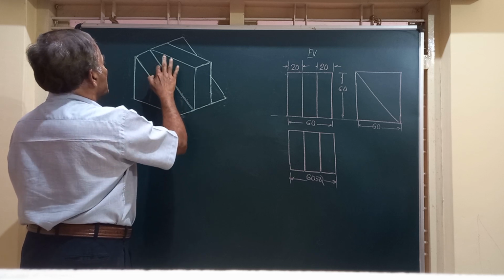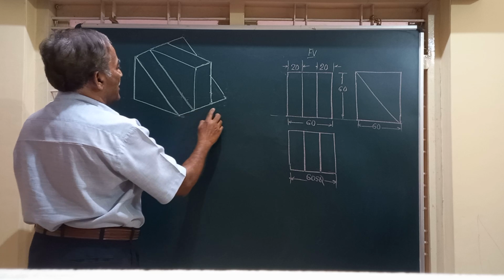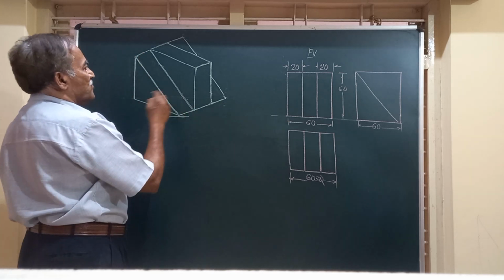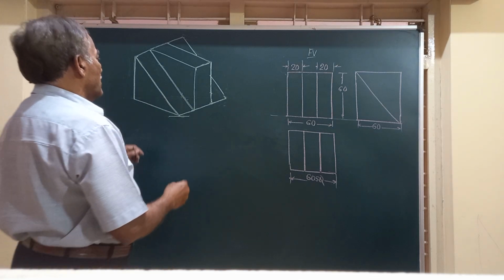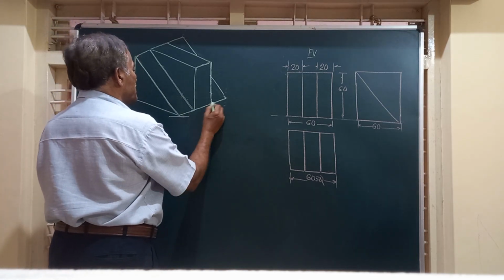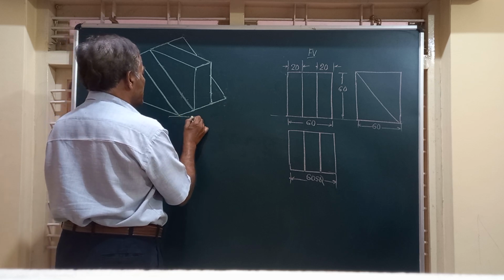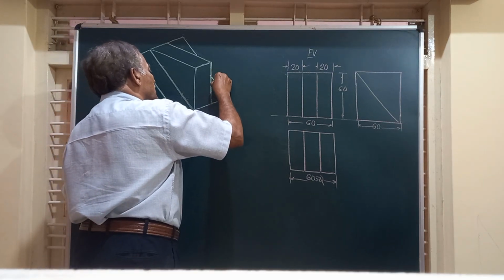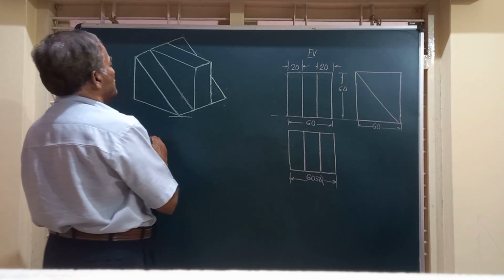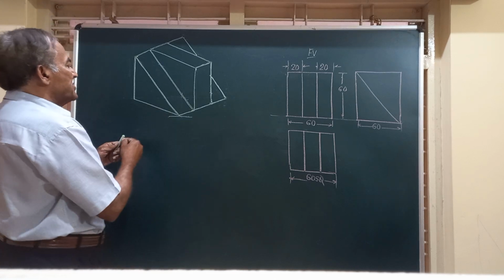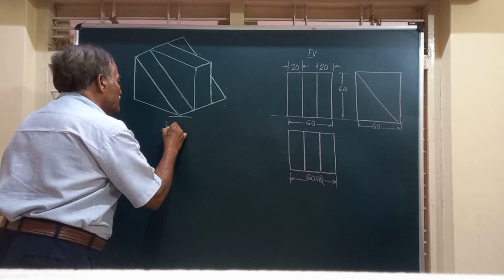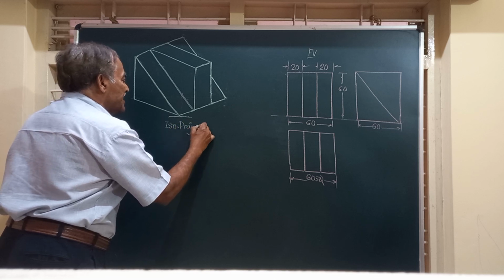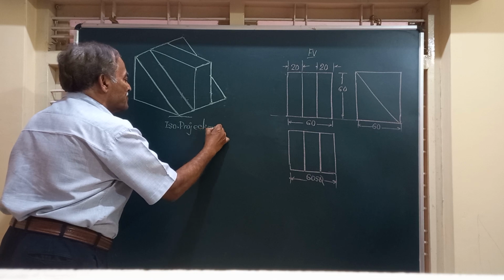So without removing the construction lines, your drawing will never look beautiful. So you can have a small line here to show that these are inclined at an angle of 30 degrees. That is, both these lines, the length and width lines, are inclined at 30 degrees to the horizontal. Friends, let me draw bold lines through all these. Remember friends, finally after completing this, you should say it is isometric projection, because we have used an isometric scale to construct this figure